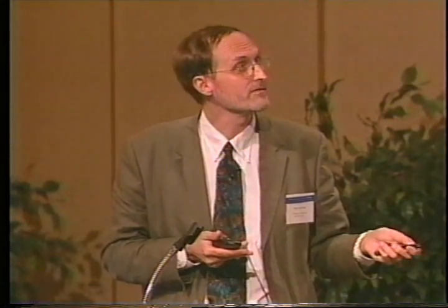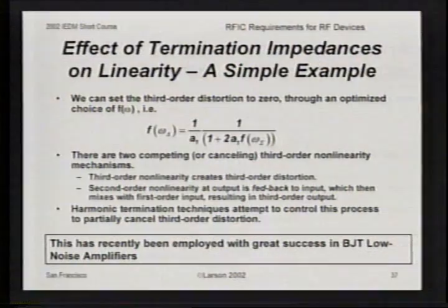And the wonderful thing about bipolar transistors is that the GM is extremely well known. It's determined by device physics. It's the DC collector current divided by the VT, the thermal voltage. So in a modern RFIC or any kind of modern bipolar process, the A1 term can be very, very precisely set at manufacture, and therefore it's actually possible to imagine that you could build a feedback network that would satisfy this equation in a very precise manner, within a few % accuracy.